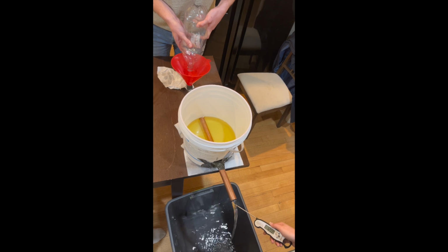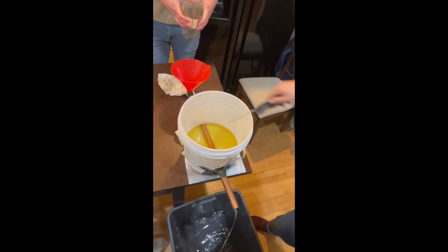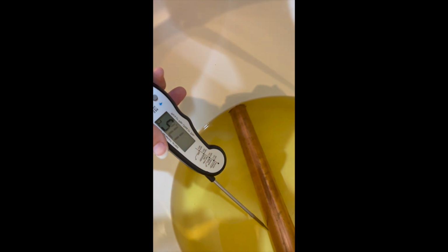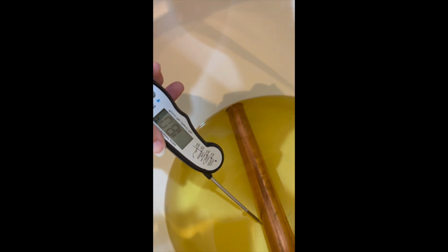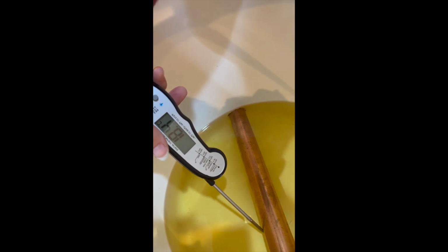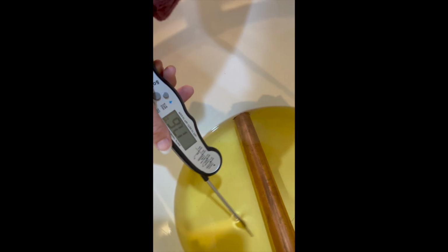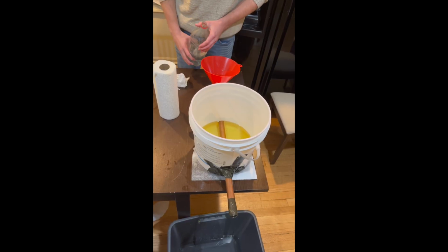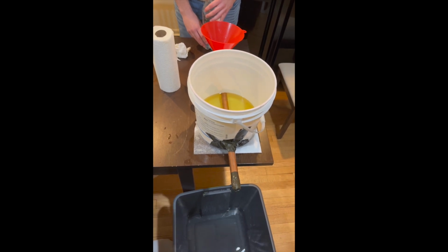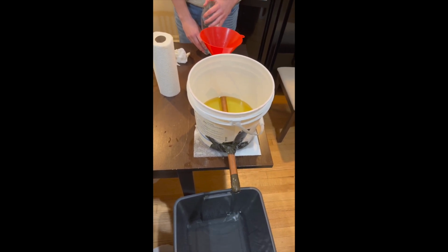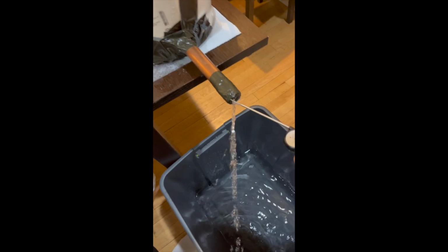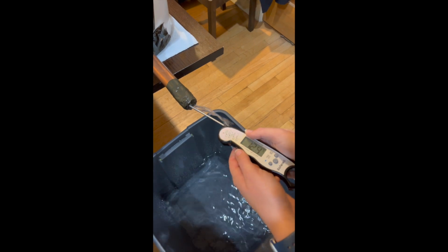As you can see in the video of our turbulent flow trial, we used a thermometer to collect the temperature values of the water immediately as it exited the pipe, and the vegetable oil directly next to the pipe. We used these values to calculate the temperature change of each fluid in each run, and we were able to compare the heat transfer efficacy of the different flow regimes. The experimental process was the same for laminar, transitional, and turbulent flow. And for the no-flow trials, we sealed off the exiting end of the pipe in order to stop the water flow and simulate a stagnant fluid.